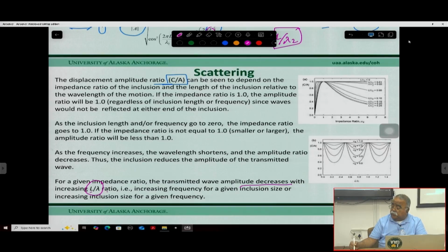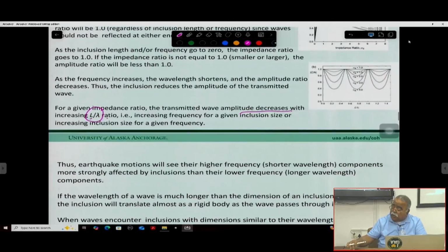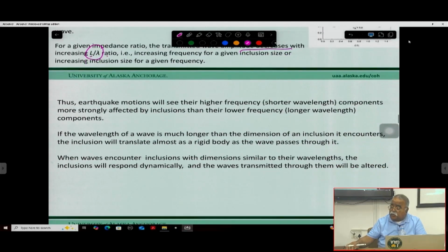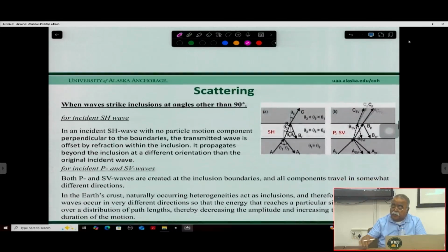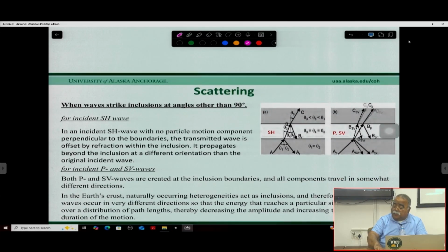So these are the scattering part and the damping part, which is basically important for the soil when these waves are incident, right? Now, if you see the incident as an SH wave in the medium, say suppose this is the first medium, so the wave comes and then it is an SH part.